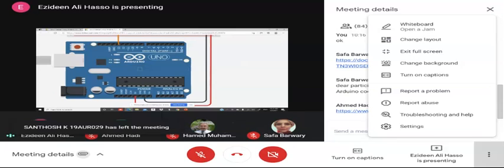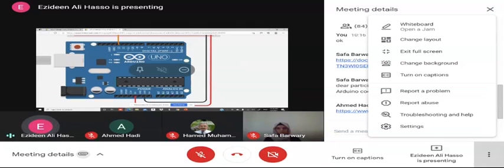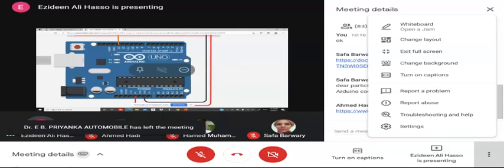Here we have the A pins. These are the analog pins. These are all digital, by the way, ones and zeros. One is 5 volt and 0 is 0 volt, because the device is 5 volt, as you can see here. This is 5 volt. And these are the analog pins. We can have analog input to our board. These are for inputs.